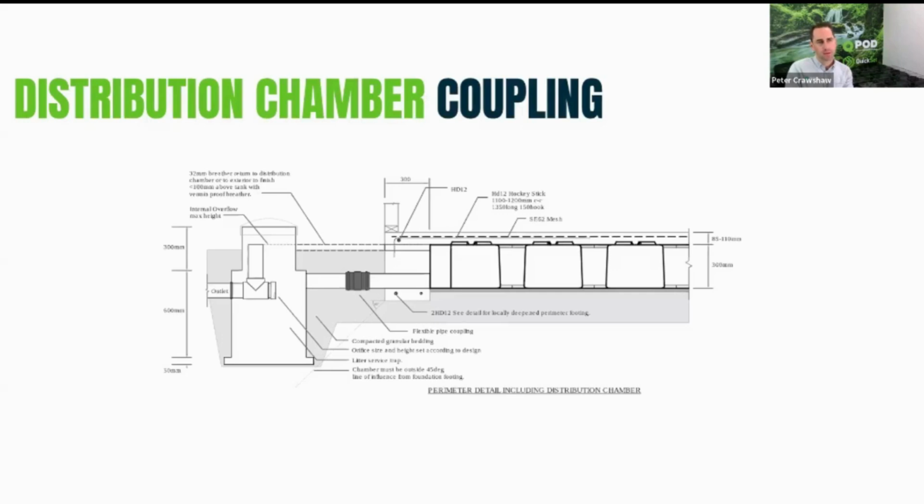You could picture the same scenario with a raft slab having air pockets in there. If your water's getting up inside those air pockets, there's possibly another underlying problem, really. So in the context and scope in which these are applied, I don't think buoyancy is a problem. As I mentioned, we're putting these in drives and slabs, putting concrete over top of them, which is bearing down through them.